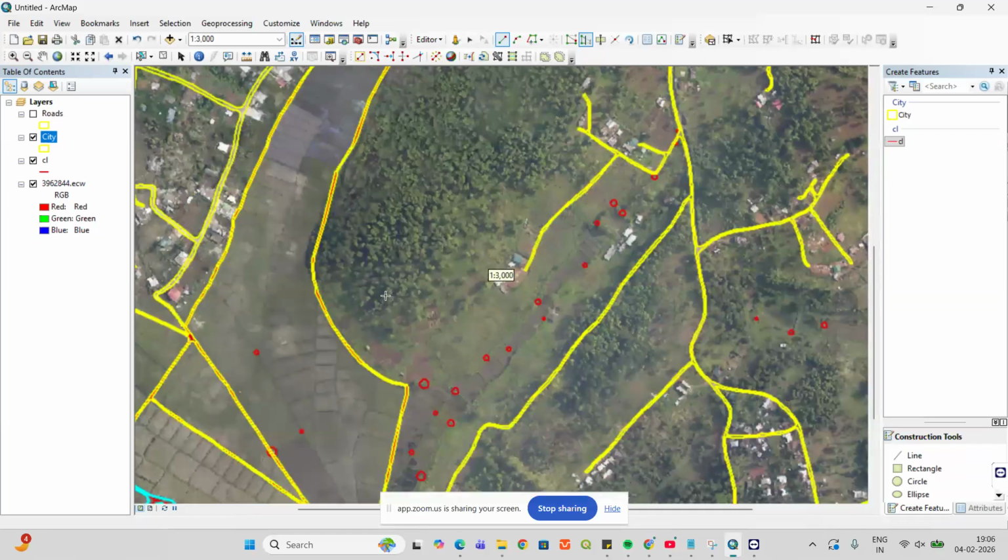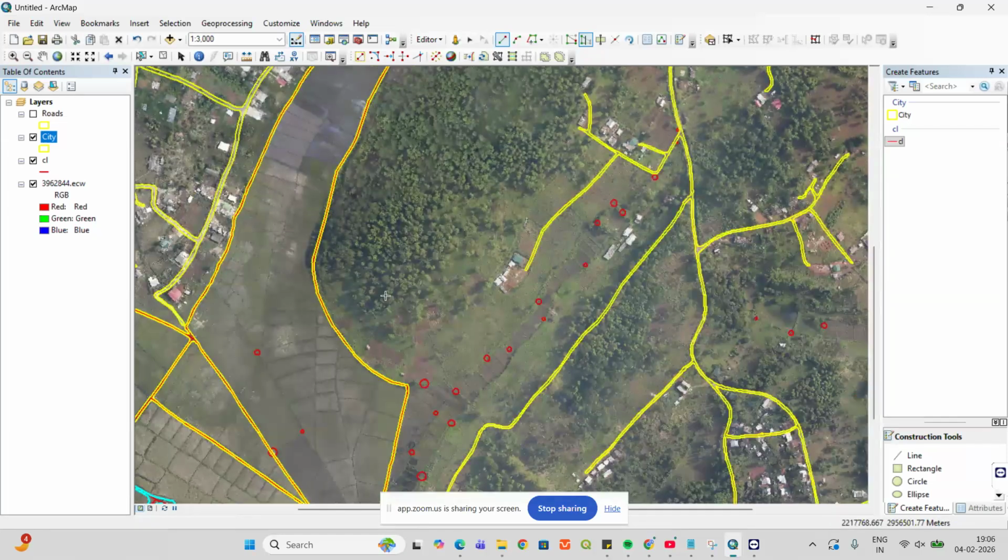Evenly, because we will not change the altitude mid-flight, like 15 this side, 15 that side, that is not possible. If we are doing it like that, then our aerial triangulation will have more work to do. Our initial process will take very much time to put it or merge it together. So when we have set one height evenly, it should be even throughout the state.